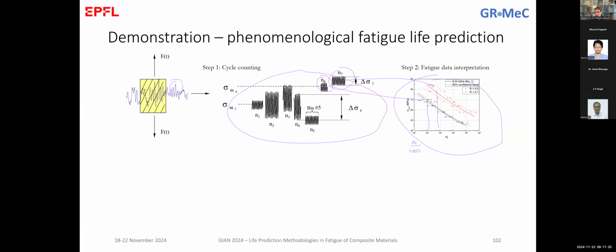And if you assume that this one is at 80 megapascal maximum stress, again, we can say that from this one, I have another D2. And we can do the same if I have another loading that corresponds to this SN curve. I have a D3 and so on. So if we sum all these, we get the total D, which defines the material integrity.